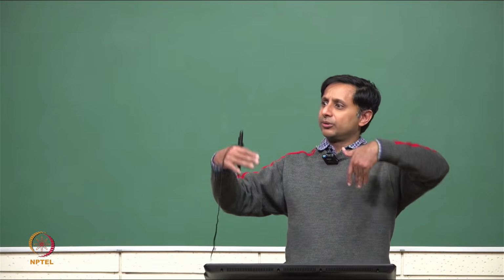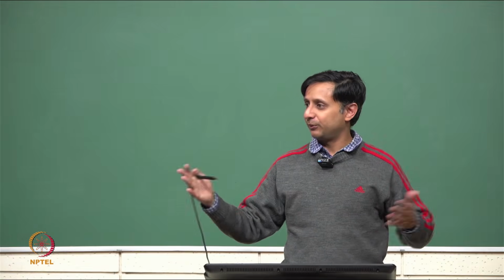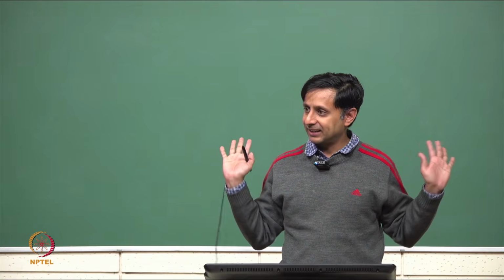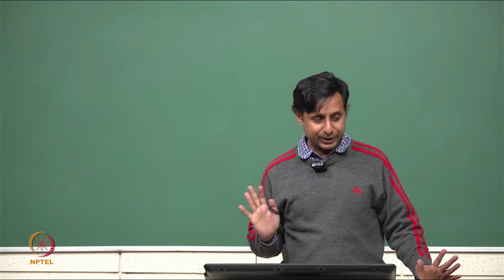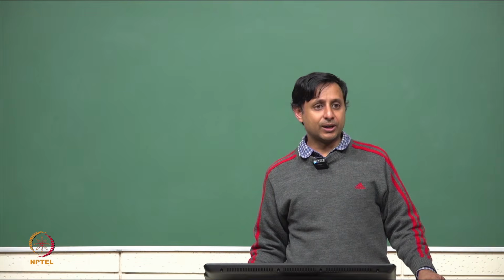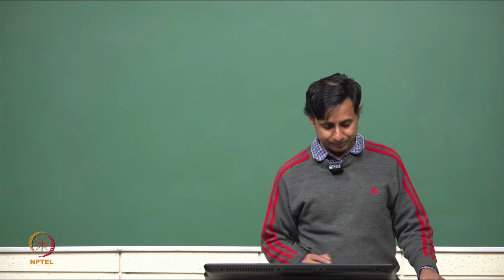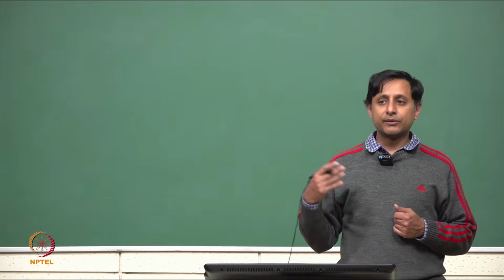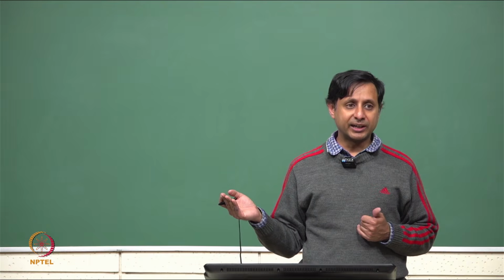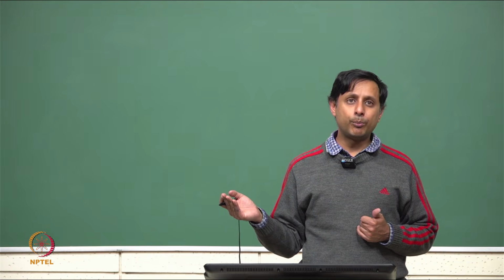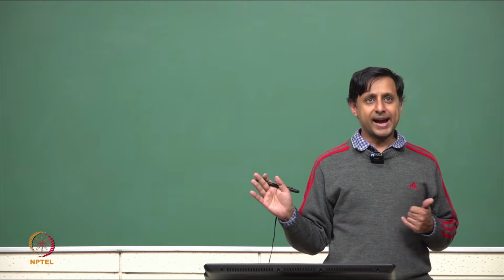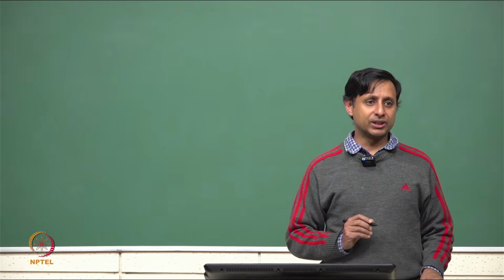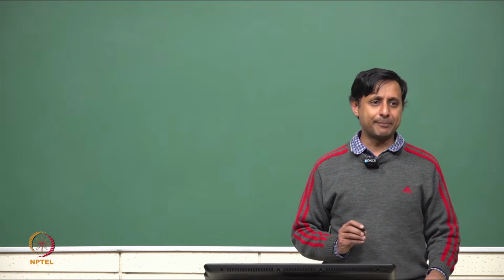And then in future you can use the 2 port network under different conditions, that is for future. For now we are going to figure out what are the Z parameters. So, what do we do? What are the experiments we are going to do? First experiment, open circuit port 2 and push I1 into the port 1, push 1 ampere into port 1.